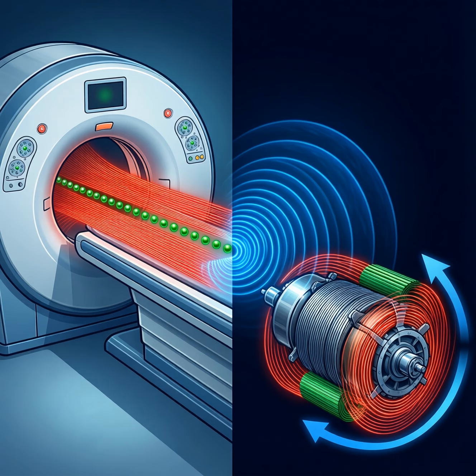images. The same principle of magnetic induction underlies electric motors, which convert electrical energy into mechanical rotation via Lorentz forces on current carrying conductors. Inside a motor, permanent magnets or electromagnets create a rotating field that interacts with copper windings to produce torque. The interaction between magnetic flux and the conductive loops generates an electromotive force that sustains rotation once